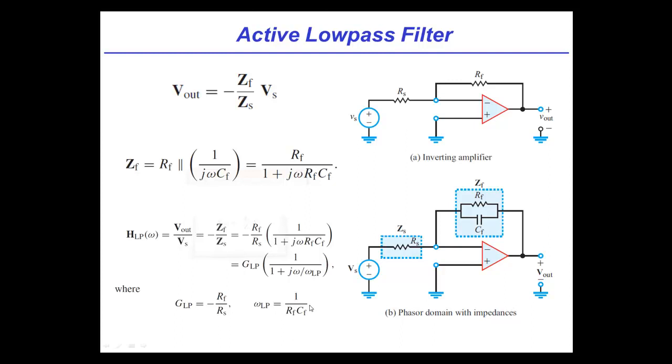This is pretty cool. So in Bode land, I would be adding these two terms, right? Because when I turn them into dBs. Exactly. So this is like our K in that old lookup. Yeah, so it'll shift it up and down. 20 log 10 of this. Exactly. Plus the standard pole. Okay, cool. That was pretty neat.